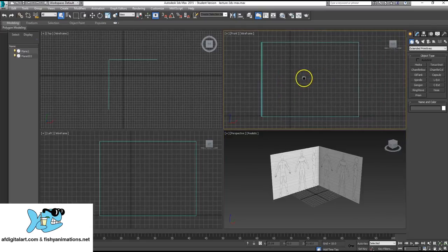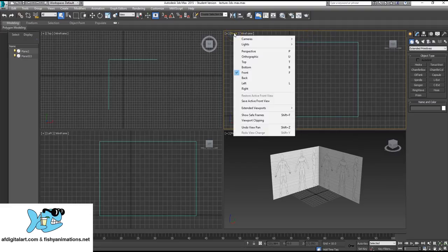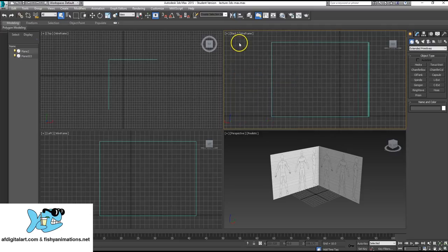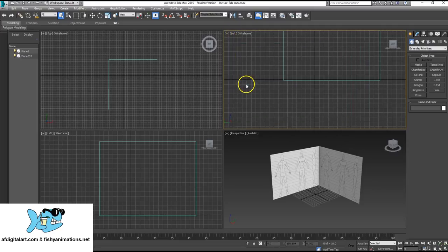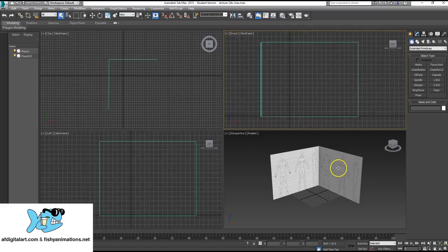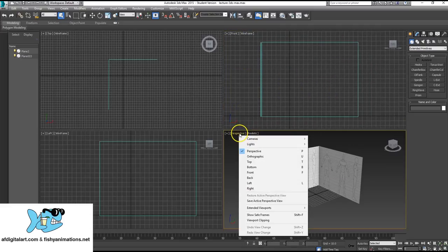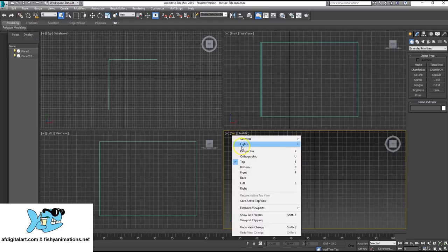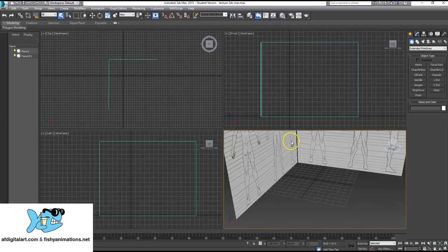Now in this case, what I can do is actually switch my front view. Notice it's wireframe to shaded solid. So if I left click the name front, notice I can actually have two views active at one time. Actually say I want to look at the back view, or I can actually say I want two left views, like so, okay? But in this case, I want the front view. This works for any quadrant, which we call these quadrants. Perspective view, I don't have to work in perspective. Come on down and say, let's switch perspective top view. Go back to perspective here.